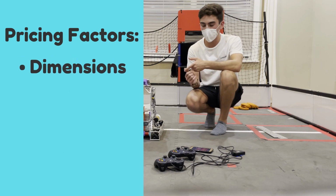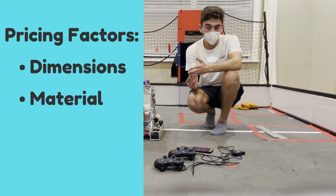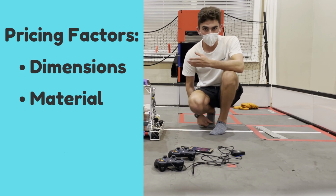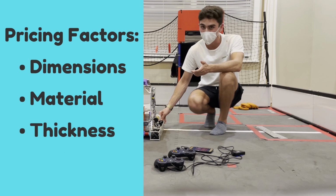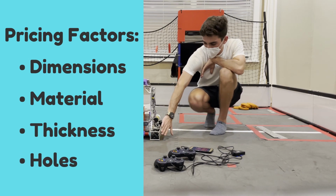Are things like how big are my parts, which often you can't change. The material, which we're going to discuss in a later video, probably the next one after this, and that will play a big role in it. The thickness does as well. If you go with a 30% thinner material, it's going to cost a pretty substantial amount less. So that makes a huge difference. And then again, the amount of holes.